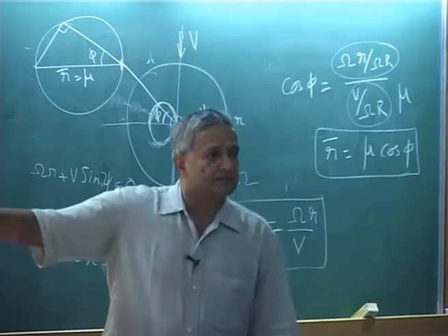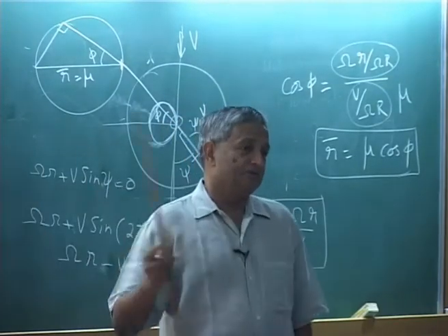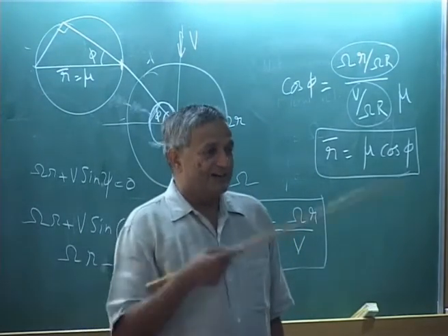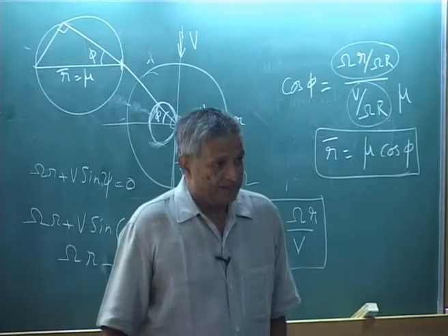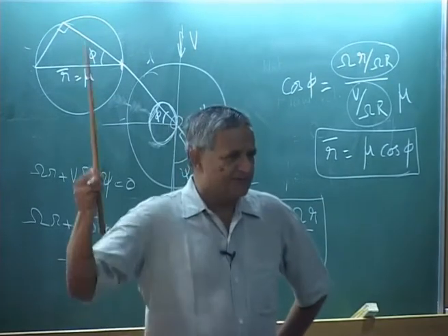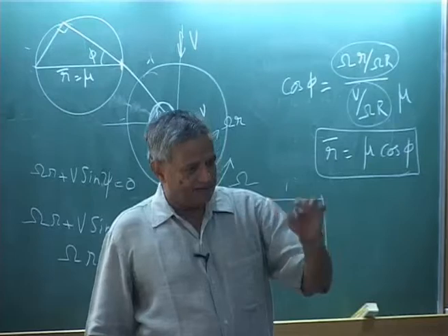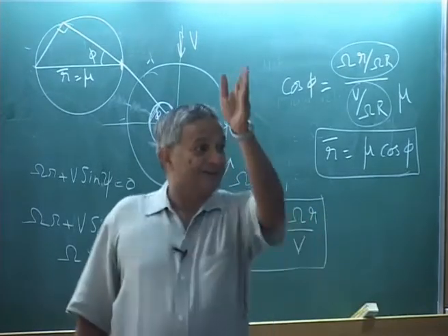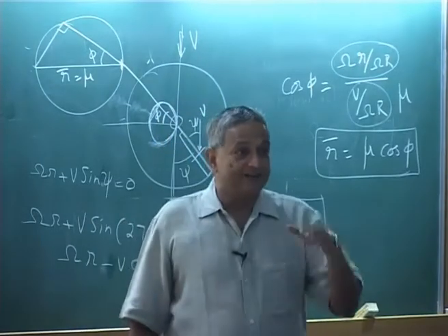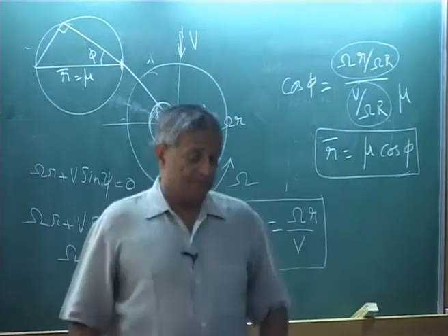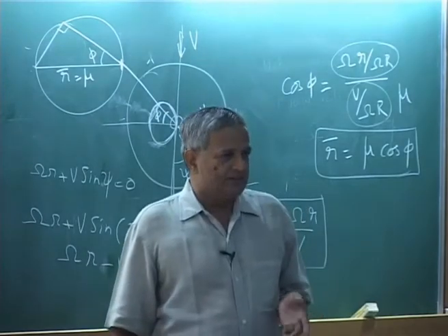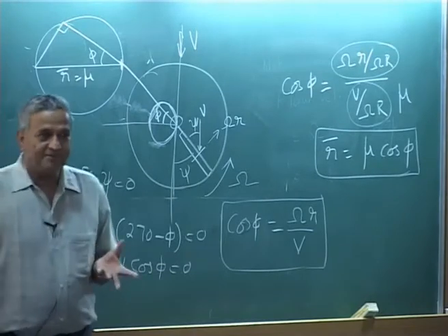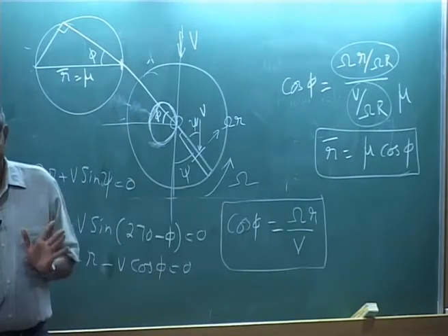As you keep on increasing Mach number, you may get into the transonic zone, you may start having higher drag, and there is drag divergence. The drag will be up to some Mach number, it will not change much, then suddenly it will start going up. That means you will start having drag divergence, increased drag, that means you need to have more power. So, these are all the problems which you start facing in forward flight.